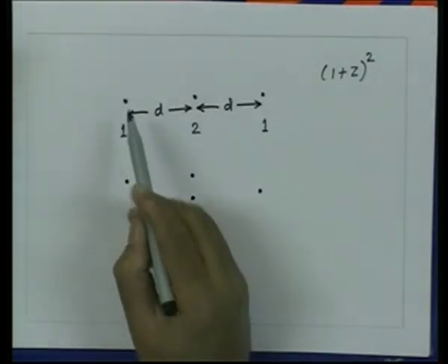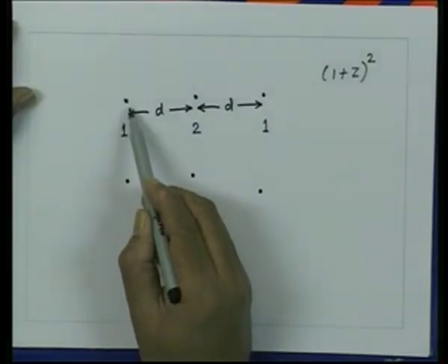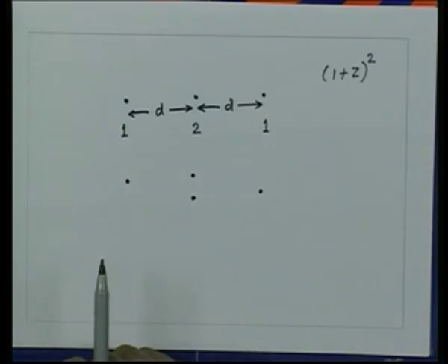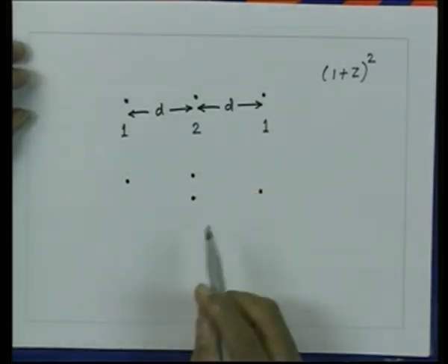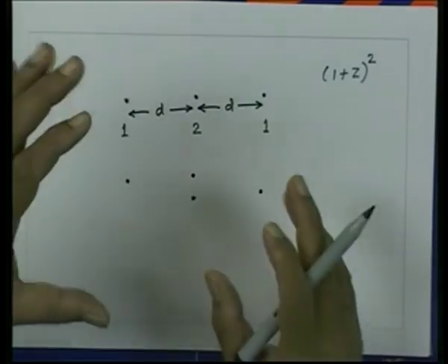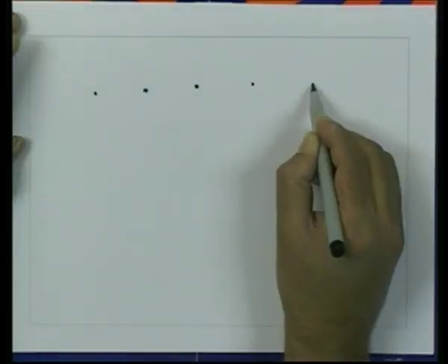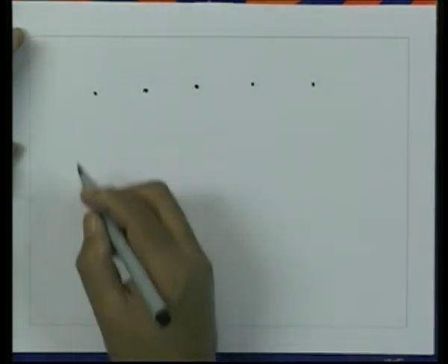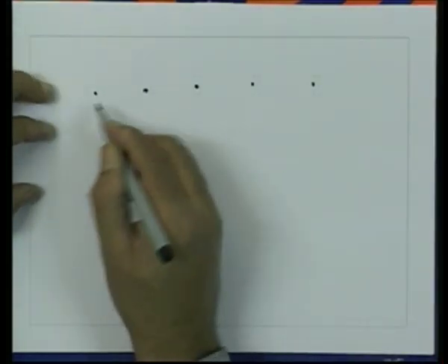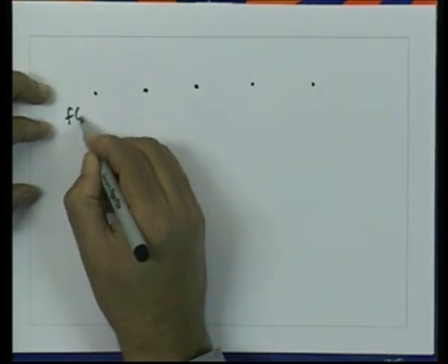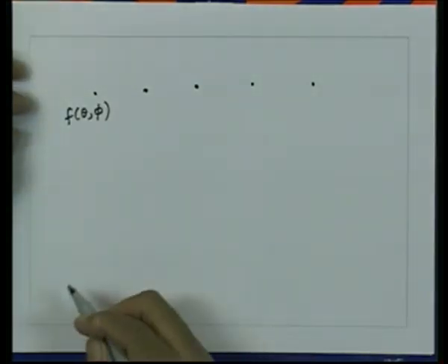Now, up till now we have considered the radiation pattern of the individual element to be isotropic. Before we investigate this array, one can ask a question: if the array elements were not isotropic, if they had some intrinsic radiation pattern, how would the array analysis change? So, the question we are asking is, if we consider an array of n elements which are no more isotropic but have a radiation pattern which is given by the primary pattern, f of theta phi.